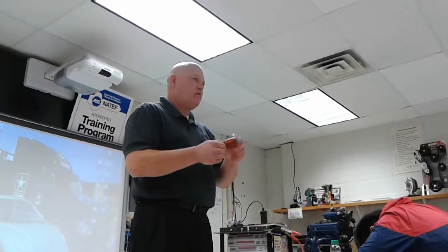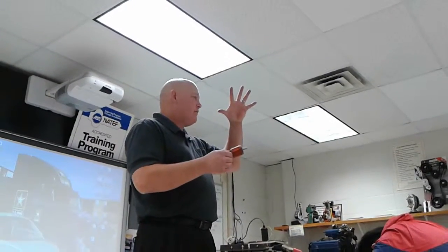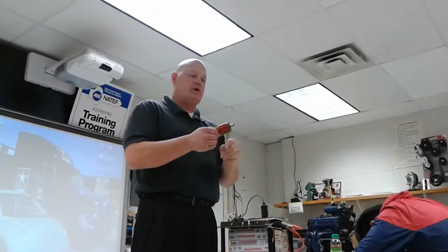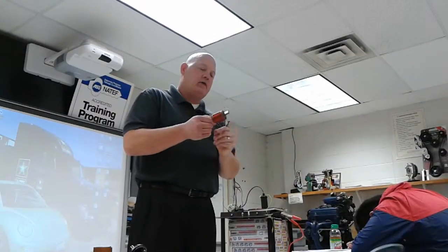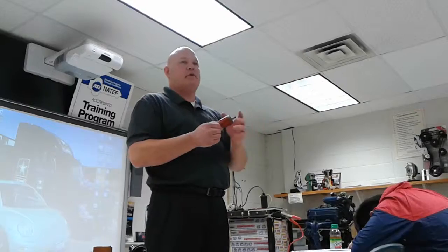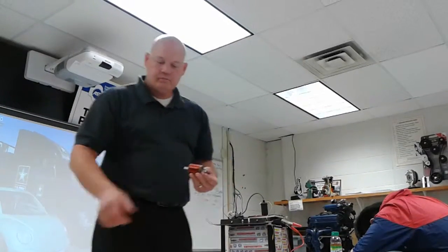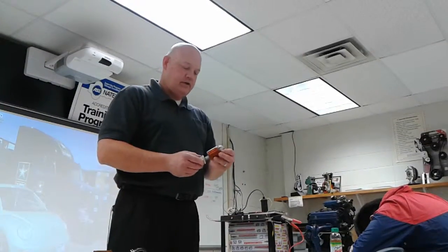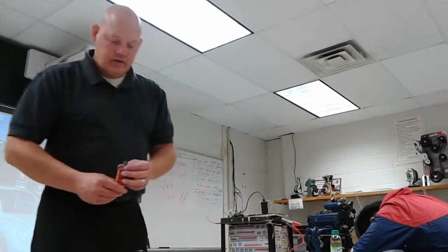We're taking a little bit of voltage, creating a gigantic magnet, and then we're going to shut it off. And when we shut it off, all that magnetic field collapses and cuts through that secondary coil, and we get the big boost of electricity. Okay? So let me give you a demonstration on what that looks like.